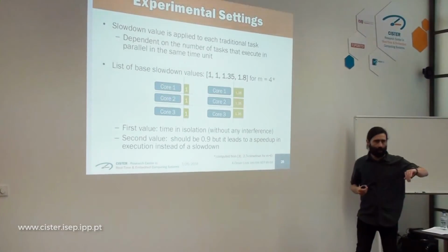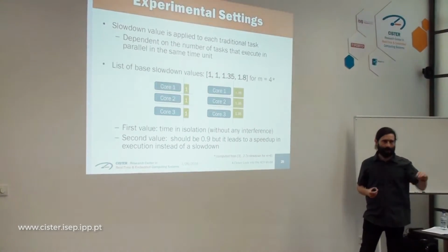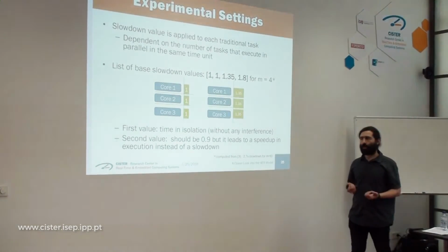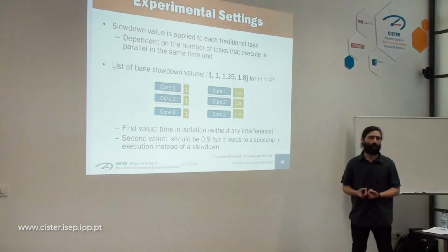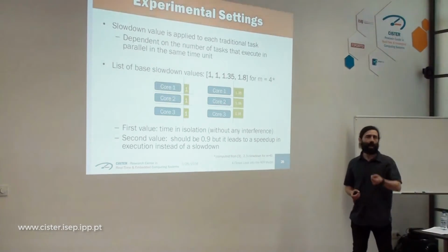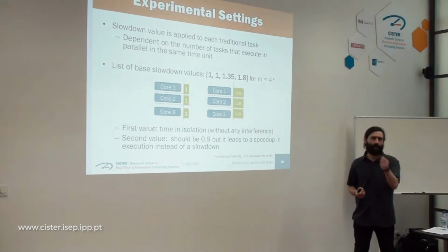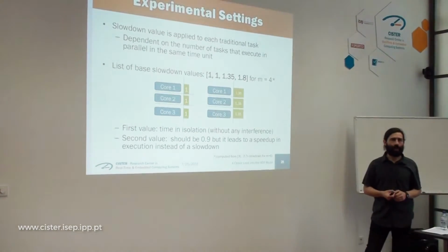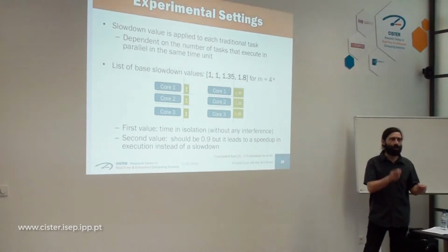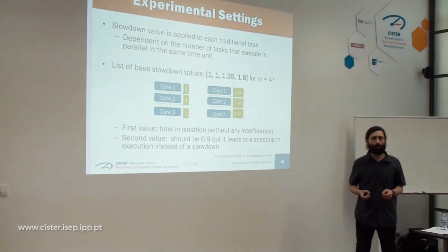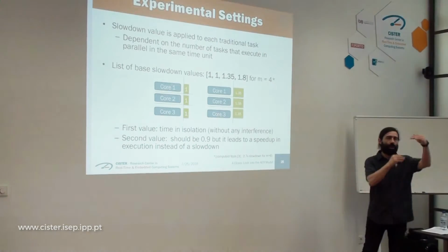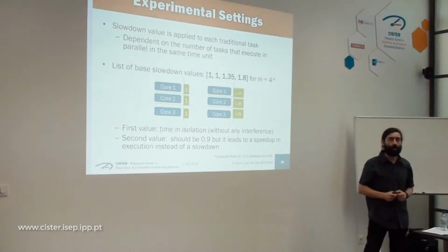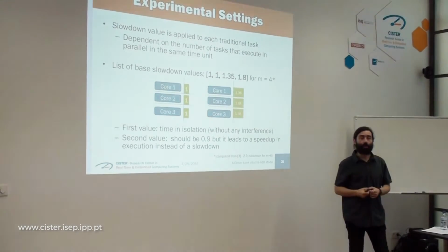No, you need to actually decouple all the memory accesses from the actual execution, and in most of the cases, and this is where the expertise of Daniel is important, because he said, no, these tasks cannot have the same execution time, because when you are doing decoupling, you are putting overhead into the task. Sometimes you need to adjust, and for the memory requests to work, you need to add certain instructions to the code to make sure that they will execute within those intervals.